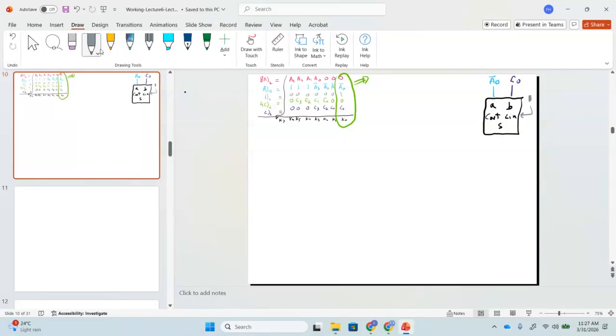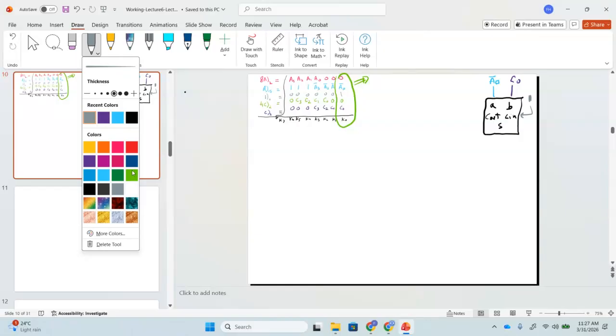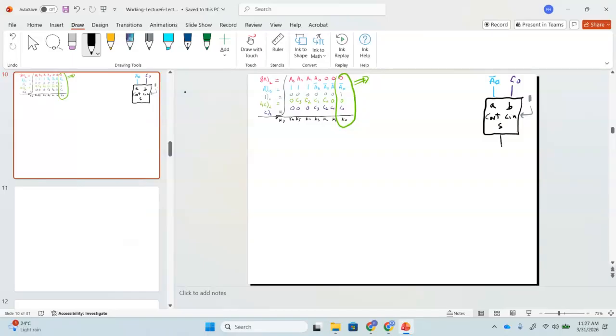What will be my output here? What should I connect to here? Can you see here this K, which is this sum? So sum will be here K0. Now please remember, we have C out, and C out from this stage will become the carry in for the next stage. So this carry out will become the carry in for the next stage.